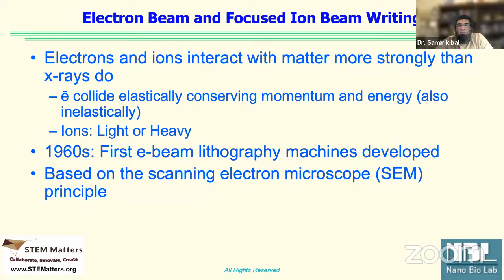Yes, Ahmed, go ahead. So I was going to ask, do we still need to use all this in a vacuum, or has it improved significantly? No, it's still required. We want to create vacuum so our electron beam doesn't deflect with particles from air. Air has particles, right? Air has so many things moving around in it. We want to pump everything out, so when I strike my beam, it does not deflect off any particles in the air.